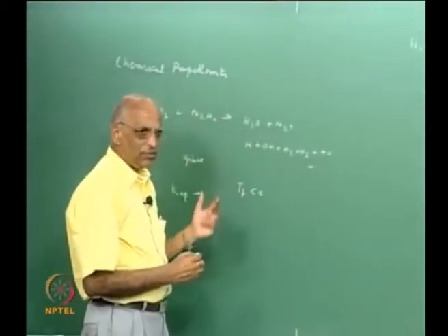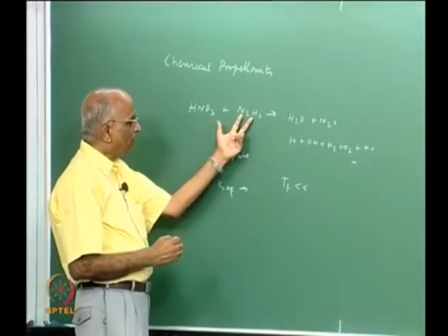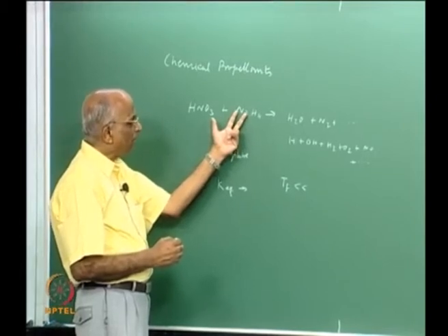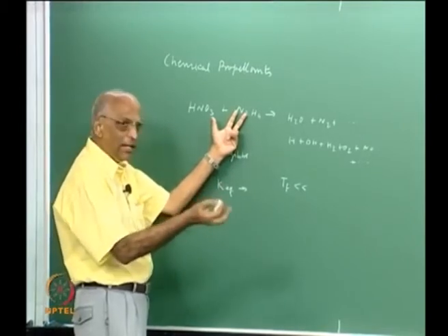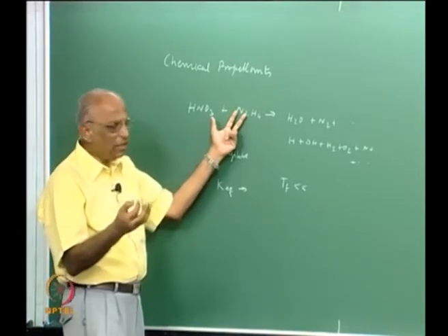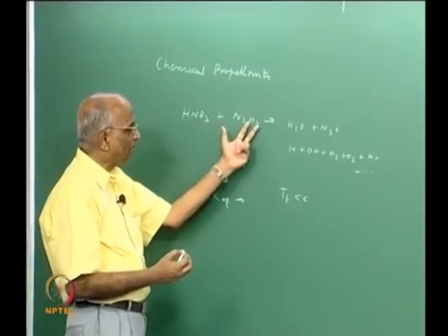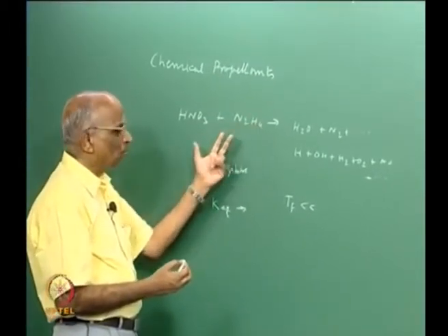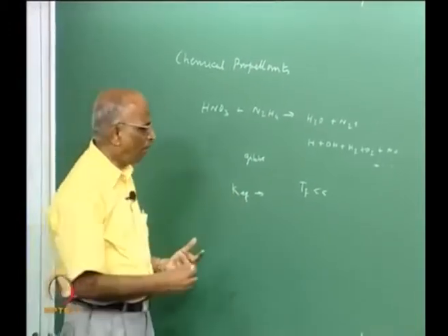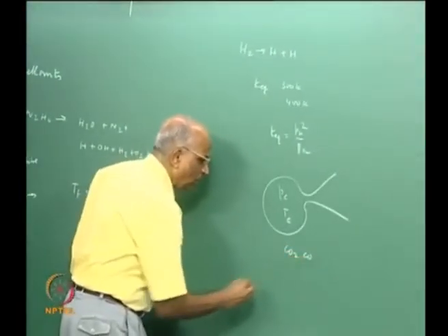When we said fuel rich, we made an assumption saying that if it is fuel rich, first the nitrogen in the fuel gets converted to N2 in the products, and it does not really give any heat. Then the hydrogen gets attacked by the oxygen and we get H2O, and then the balance goes to react with carbon, and this is how we did it, and it was an approximate way of finding out what is the value of CO2, what is the value of CO.